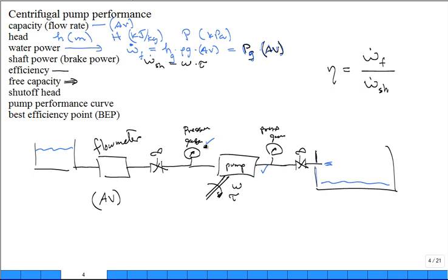If it does that, the pressure difference or the pressure gain across a pump is minimal. It's just sort of like catching it and slinging it without adding any pressure to it. That's the highest flow rate through the pump possible. Other than that, you're going to be forcing it through with a pressure that's going to be higher on the inlet than the outlet, right? Don't do that, right? This is a free capacity. So at the free capacity, your delta P gain is 0.